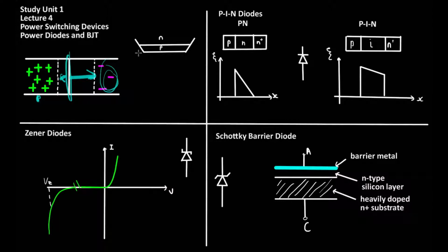One of the ways in which the thermal and current problems of p-n junctions with lightly doped n areas are compensated for is by having asymmetrical doping profiles and asymmetrical silicon structures. So in this example here, the p region is quite narrow in comparison to the n region over here. The problem with this is that at the edges of the junction over here, there are breakdown problems which need to be compensated for. Ways in which these edges can be protected is by making use of guard rings or by beveling the silicon region in order to avoid high breakdown voltages appearing at the edges.